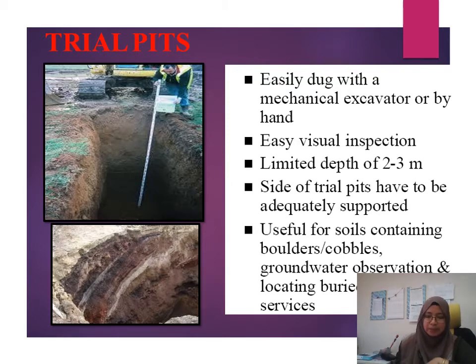But the main disadvantage of a trial pit is the depth. We can only advance the observation by 2 to 3 meters only. We cannot go deeper than that.